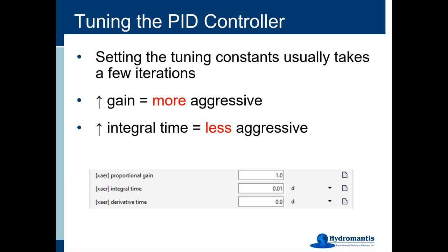There's no perfect controllers that are always going to keep everything right on the set point all the time. But what you want is something that is always coming back to the set point and not doing it in an unrealistic kind of way. You don't want to be too aggressive because then it's going to cause a lot of changes to your pump. And that might not be even realistic at all for the type of system that you have out there in reality.